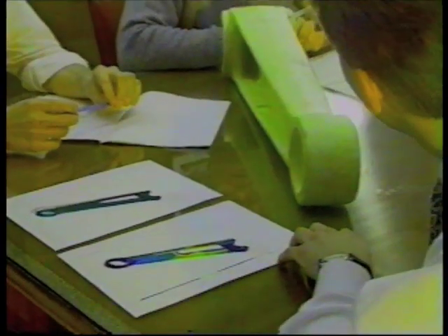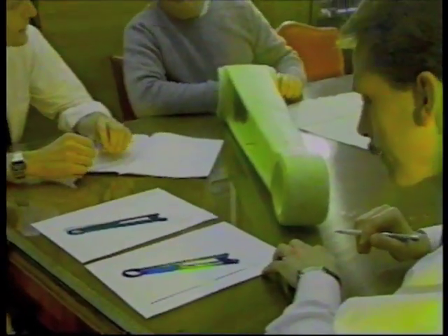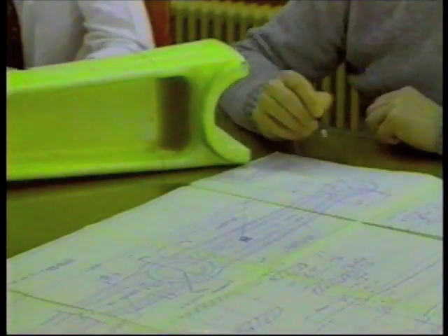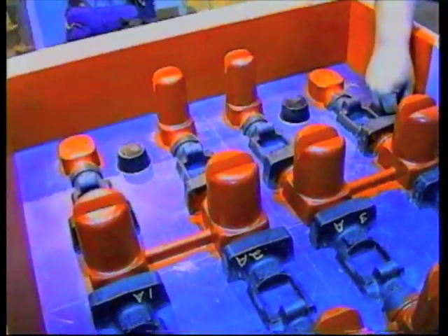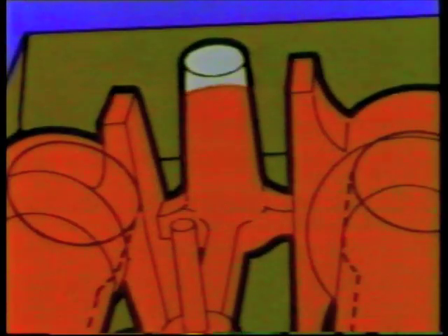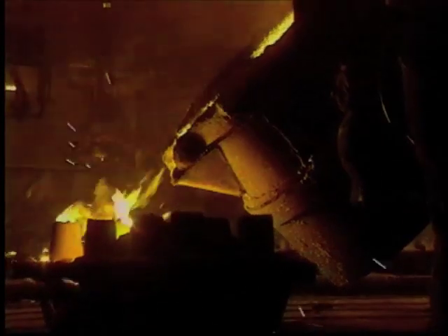The foundry and the design engineer should work together to design a casting that can be made and used reliably and cost-effectively. In addition to mold and core making, gates and risers must be considered in casting design. The foundry must add a gating system for filling the mold with liquid steel. The gating system must allow the liquid steel to fill the mold cavity without eroding sand or splashing around.